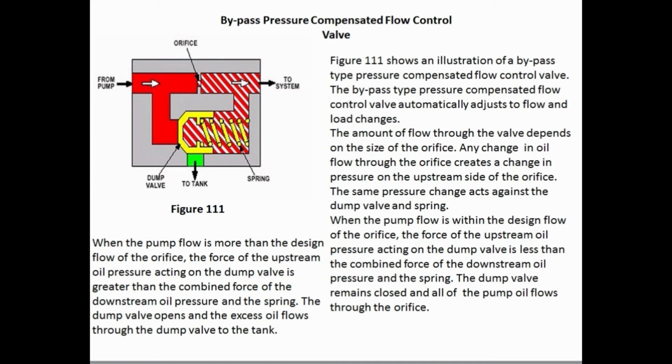The force of the upstream oil pressure acting on the dump valve is less than the combined force of the downstream oil pressure and the spring. The dump valve remains closed and all of the pump oil flows through the orifice.